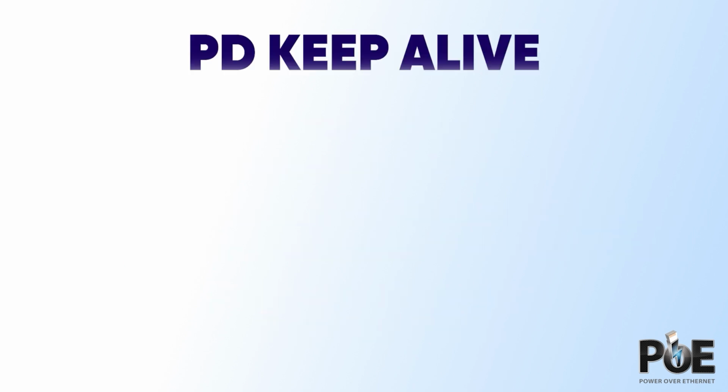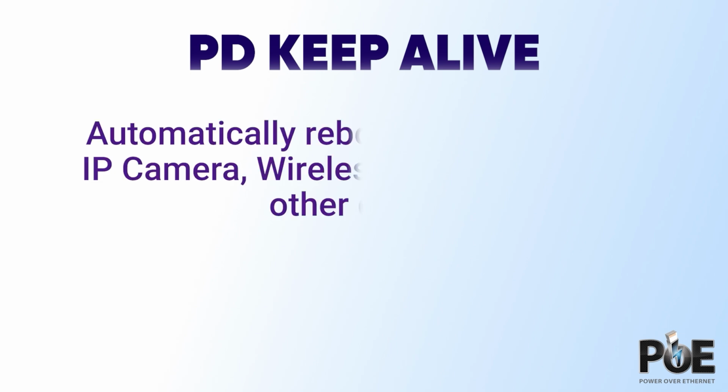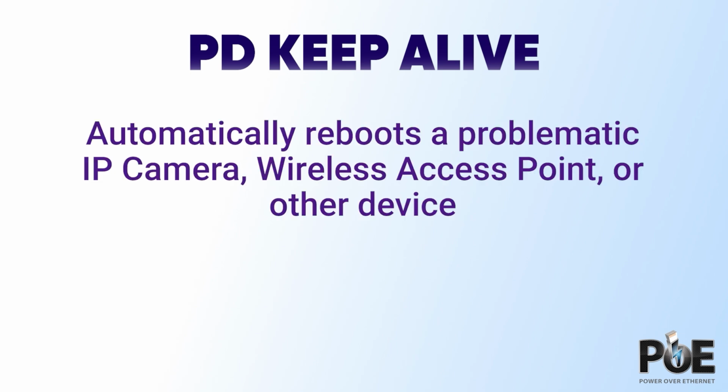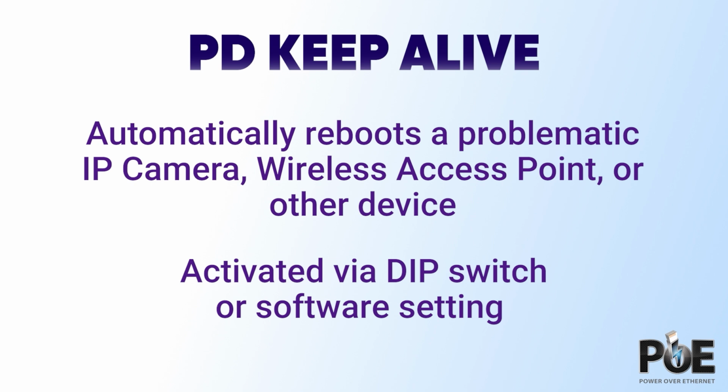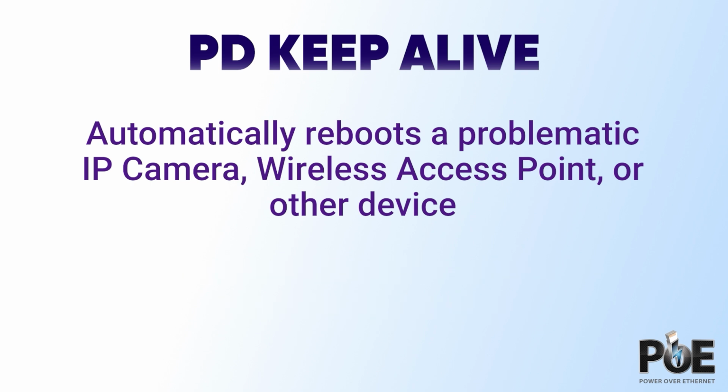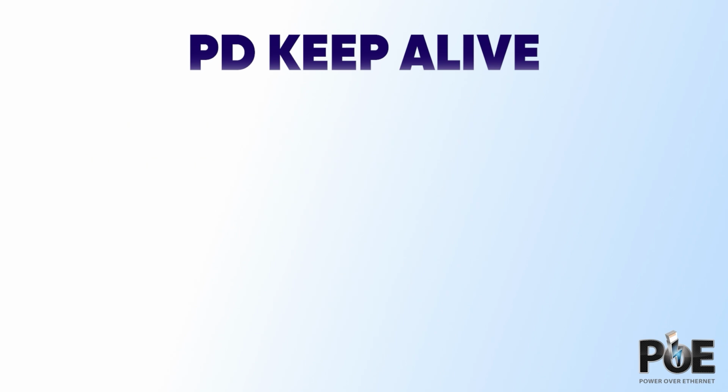Various PoE switch manufacturers support a PD Keep Alive feature. This feature can be activated on a PSE port either via a dip switch hardware setting or software setting. Powered devices like IP cameras and wireless access points may occasionally lock up and require reboot. The PD Keep Alive feature, when enabled, can address this automatically. An example of the process follows.